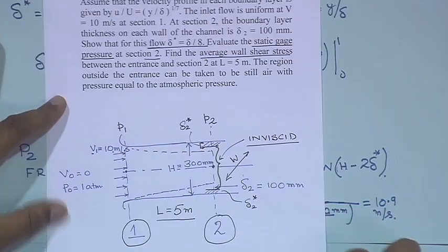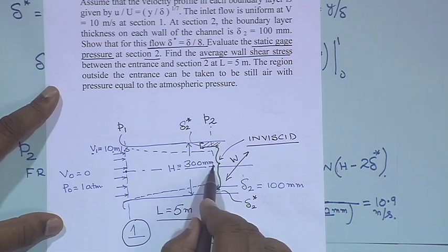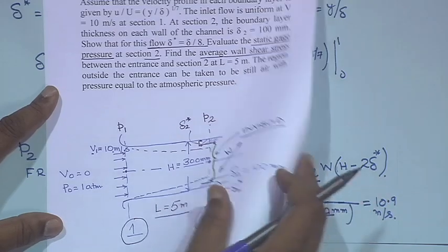And the moment it becomes inviscid, then I can apply Bernoulli's equation across any streamline, so to say. So, between point 0, which is outside of the duct, and location 2, since the entire flow starting from point 0 all the way up to 2 is now inviscid flow, I can write Bernoulli's equation between these 2 points. So, that is what I am going to do next.